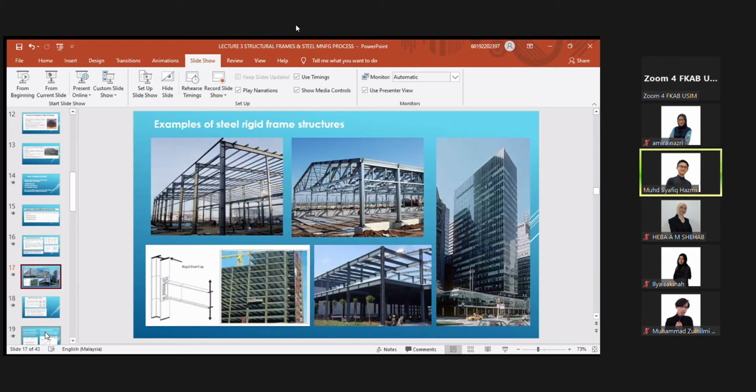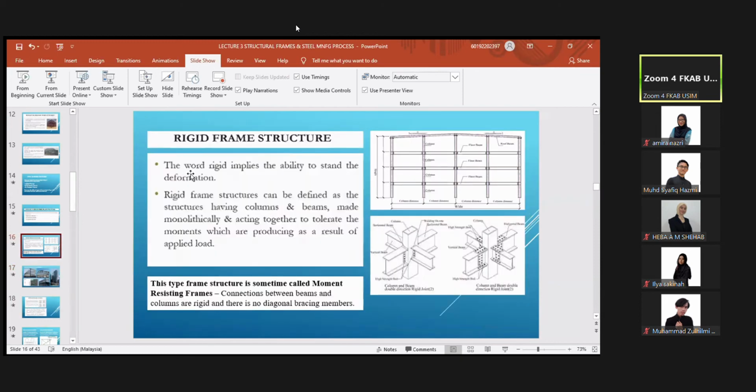Diagonal, what is diagonal? Okay, good question. Diagonal means that this open frame, from the roof beam to the bottom here, there is a bracing here, another frame here. Diagonal frame. Now the rigid frame is here, but when we come to brace frame, you can see diagonal here. Diagonal is jointing from an angle like this to make the frame rigid. We will talk more about diagonal later.